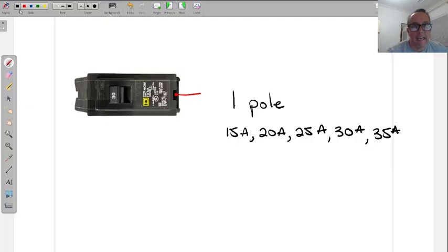Now, when you go to test this breaker, this is the part I want you guys to understand also. The breaker is a switch. Power comes in from the side that you connected to the panel. It's always over here that power comes in, and power goes through the breaker and distributes out the back side of the breaker, or where your conductor lands. This is where the power goes out through.